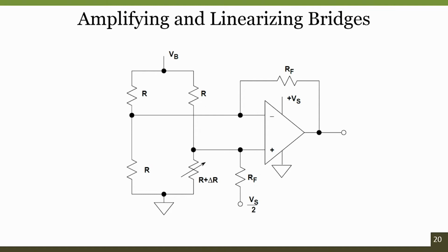So, that is one disadvantage of going with a difference amplifier, because as we discussed, the difference amplifier will have input resistances both on the negative terminal side as well as the positive terminal. In between the output from the previous stage and the direct input to the inverting or non-inverting terminal, it always contains an input resistance.